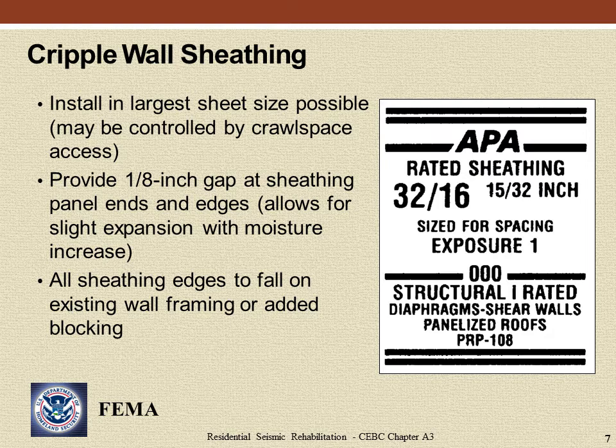Plywood is fabricated at a very low moisture content, and it is typical for the plywood to expand somewhat due to higher moisture content when installed. For this reason, 1/8 inch gaps are required at sheathing ends and edges. It is recommended that these gaps be provided not only between abutting sheathing sheets, but also between panels and abutting framing. All sheathing edges are required to fall on and be edge nailed at 4 inches on center to framing, including studs, top plates, sill plates, or blocking.